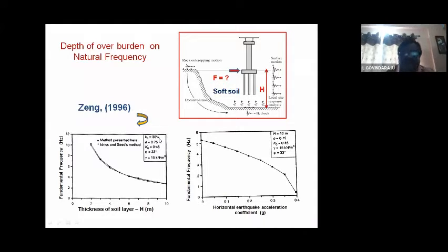It means acceleration due to gravity is about 9.81 meter per second square. Approximately 0.3 g, or 3 meter per second square acceleration. And he considered arbitrarily one soil stratum having a void ratio 0.75, coefficient of earth pressure at rest condition 0.45, and angle of friction 33 degrees. These are all properties of the soil, and gamma, the unit weight, is 15 kilonewton per meter cube.